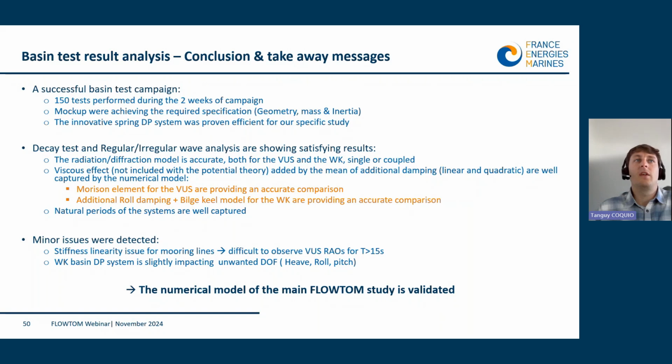To conclude on this basin test analysis, it was a successful basin test campaign. We spent 2 weeks in the basin. Around 150 tests were performed. The mock-ups achieved the required specification, be it for the geometry, mass, and inertia. The innovative system that was proposed by Eframer to represent the dynamic positioning of the body was very efficient and did not pollute the other degrees of freedom much, so we were very happy with that.